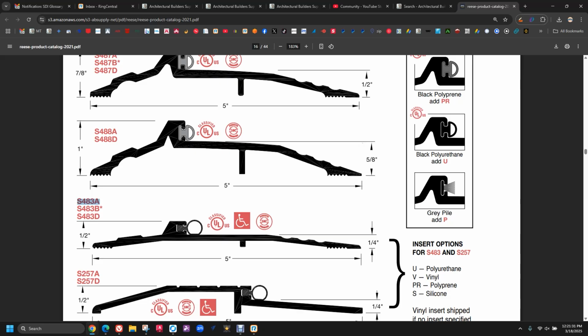So this type of bump up style or panic or latch track does a number of things. First of all, it's a bump up style. Your door is going to reside in this area, make a seal here. It's handicap compliant because it doesn't exceed a 1/2 inch, and where it exceeds a 1/4 inch in height, that change does not exceed a 1/4 inch in height is what I'm driving at. This is okay, but if the 1/4 inch to the 1/2 inch was any taller, it would not be compliant. So it's bump up style, it is handicap compliant, and it's a latch track.